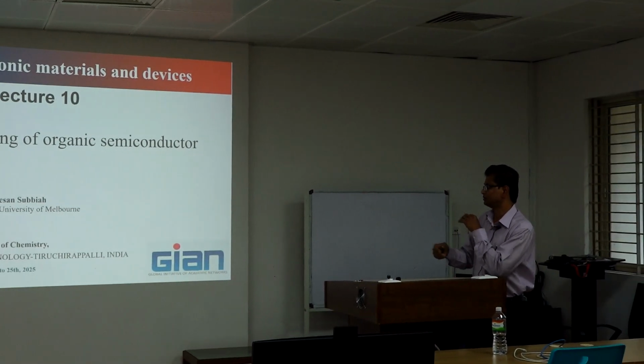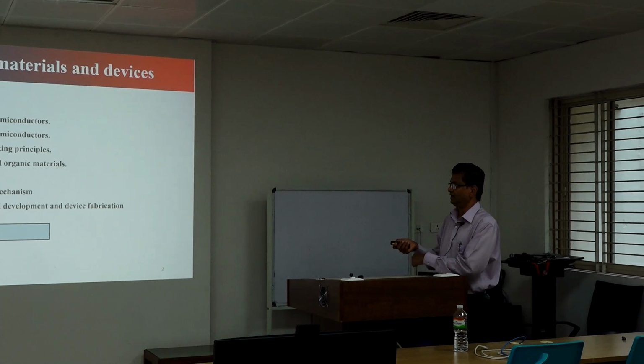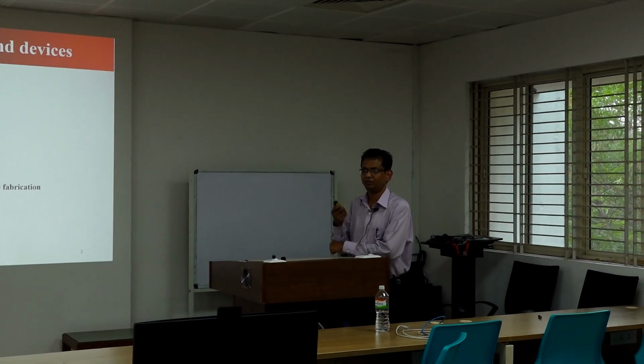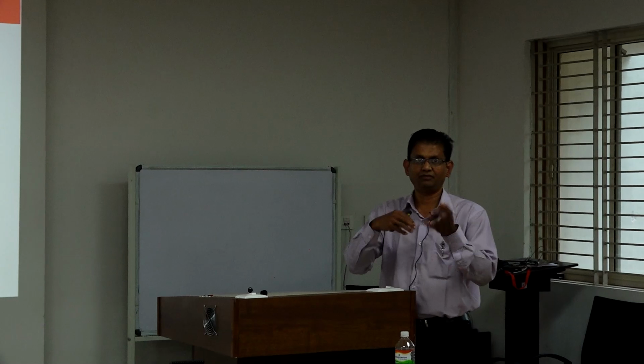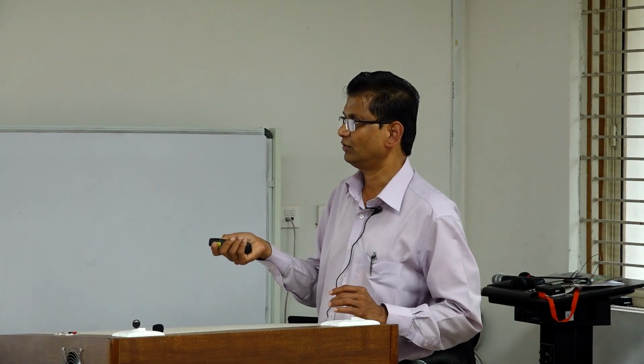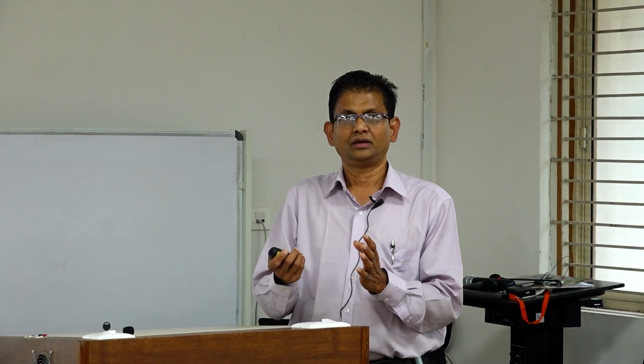if you see, material design is very important according to applications, which band gap you are using and which HOMO level you are using, everything. Okay, we got a material and we got all the photophysics and everything. Then we make a good device, and interface is very important, both in OLED and any device, because the charge extraction and charge injection is inorganic, but all the photophysical processes are happening in organic. So the organic and inorganic things are entirely different. We need to have a suitable interface layer for efficient performance.